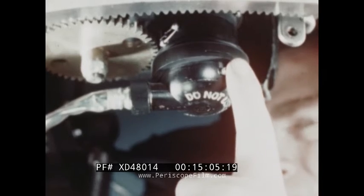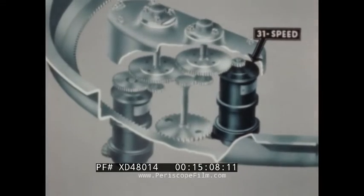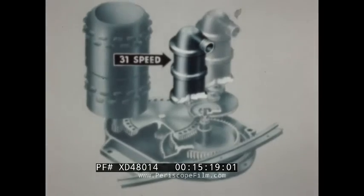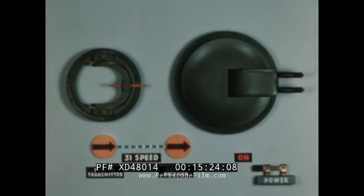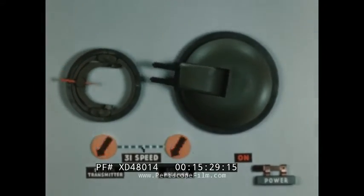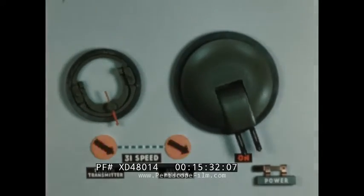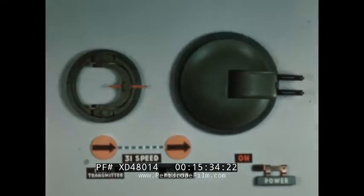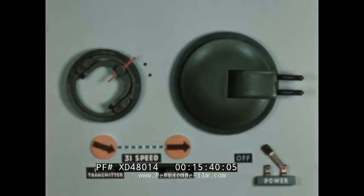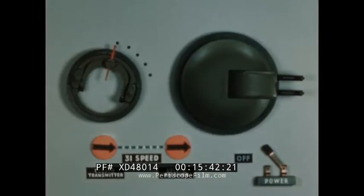A Selsyn transmitter on the sighting station is geared to the sight at a ratio of 31:1. A receiver on the turret is geared to the guns at this same ratio. Thus, one revolution of the sight turns the transmitter rotor 31 times. The guns and receiver follow likewise. With the power off, note that one turn of the sight will align the Selsyn transmitter and receiver 31 times.